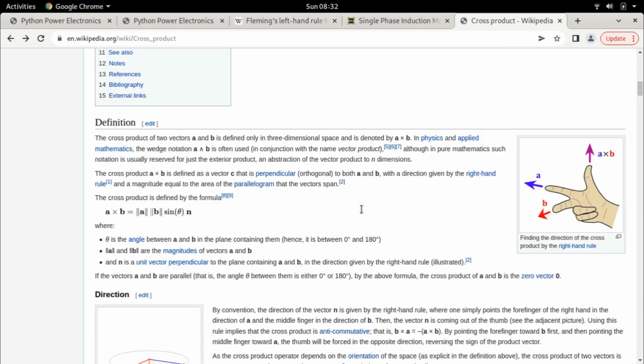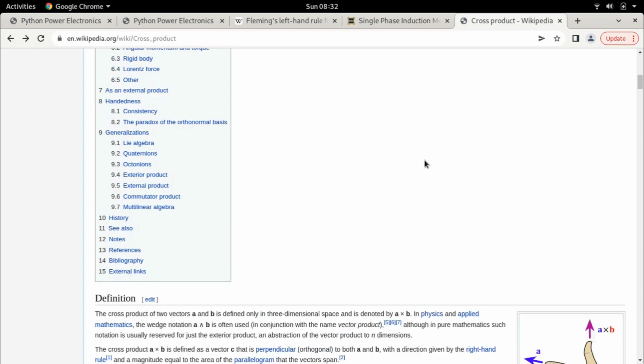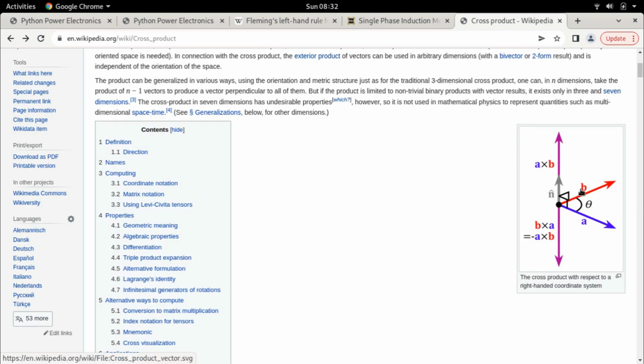Alright? We can again use something like a hand rule. Now, at this point, let us not talk about the actual hand rule because we already introduced the left hand rule and there will be a confusion here. But what is important to remember is that we can use this cross product concept to calculate the mechanical force in exactly the same way, by saying that this mechanical force is going to be in a plane 90 degrees to the plane formed by the current and the magnetic field.